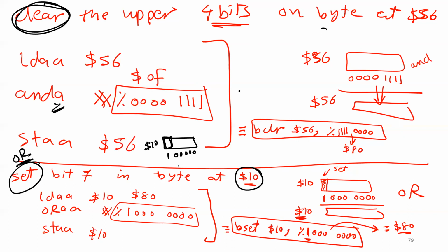I have to put zeros. So the bit you wanna set, put 1. The bits you don't want to change, put zeros for sure. Make sure, because this sometimes confuses students. So they have to be 8 bits. Sometimes I'm lazy to write the 8 bits, okay? But this confuses students. So let me see here. This is okay.